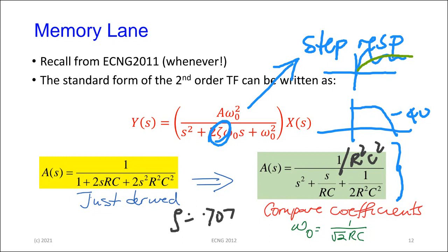Anybody remember, in the second order system, when zeta was 1? We saw that it was overdamped, underdamped, or critically damped. Anybody remember? It was critically damped, right? So this is a little bit underdamped. If you were to plug this in and plot the time response, it would be a slightly underdamped response, which means that there might be a little tendency to have some overshoot in the time response.